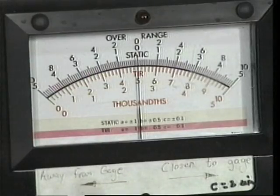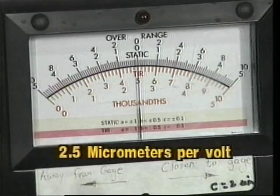The separation changes can be read from the analog display, or as we will demonstrate in this experiment, can be recorded as analog signal voltages. The signal voltage range is plus or minus 10 volts. At 2.5 micrometers per volt, this equates to a measurement range of 50 micrometers, which is more than adequate for our experiment.